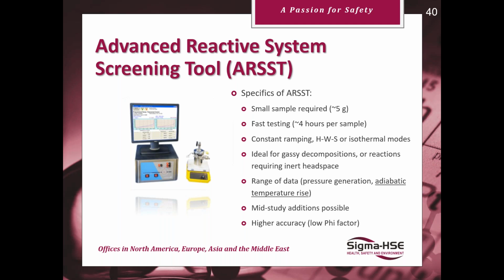Now this system is great for gassy decompositions or reactions that require like a nitrogen headspace, for example, just due to the design of the vessel. It's good for gassy systems. So again, it gives you a range of data, your pressure generation, and your adiabatic temperature rise, which is a key one again. This one is a great one for mid-study additions.